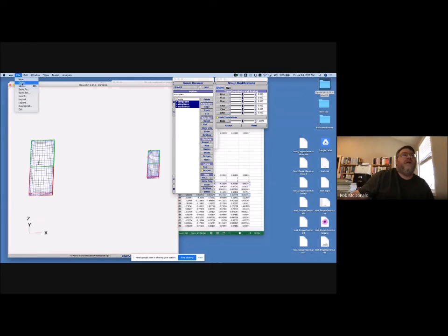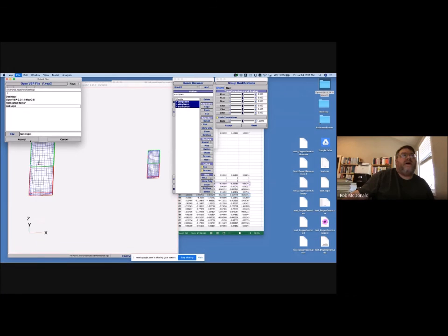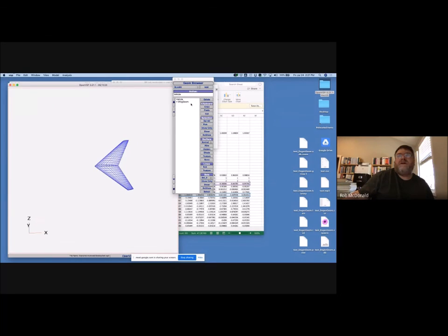And so let me go back to our example file. And here in our example file, where we've twisted the wing down at the tips, that's essentially this outboard. You can think of the tip of this wing as acting like a horizontal tail, right? The tip of this wing is after the CG, because the CG is going to be up here someplace, and it's pushing, it's twisted down.